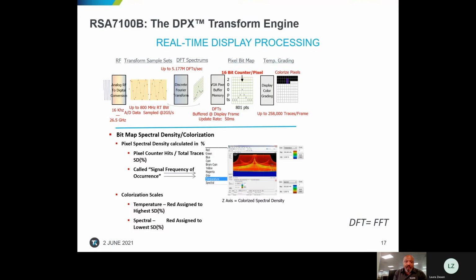Now, this is important for a lot of our RF customers who are looking for performance over a particular band of interest and looking for signals that may be hidden by a traditional swept analyzer, which is not moving at a rate fast enough in order to capture the signal that which may be aperiodically pulsing on. In this case, it may represent a jammer, or it may represent someone who means to do nefarious action to the target receiver.